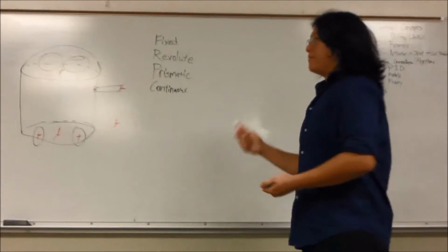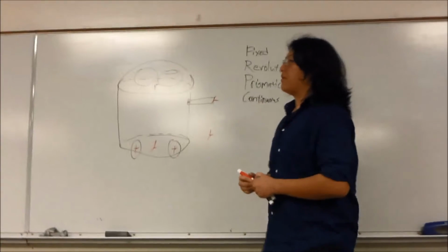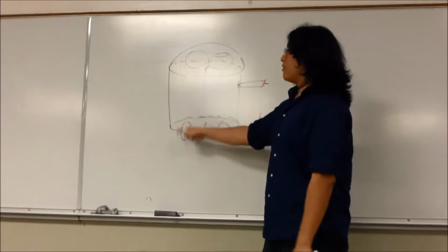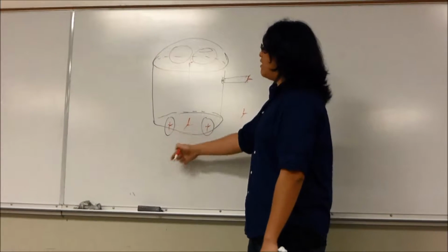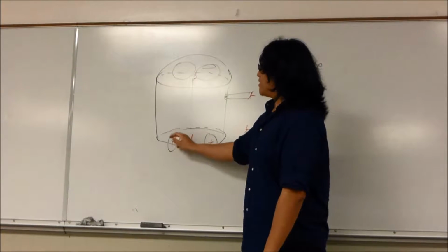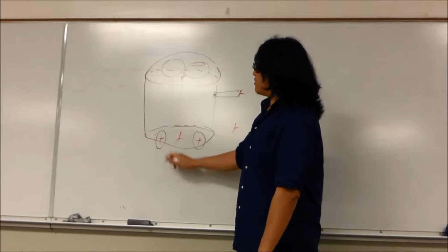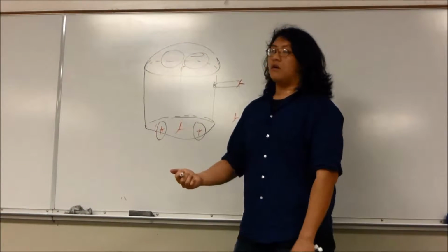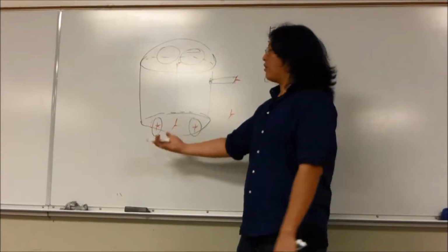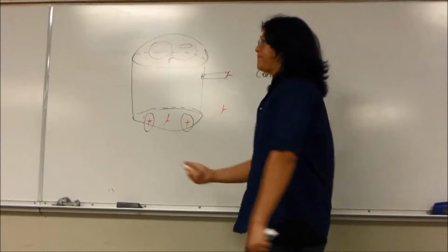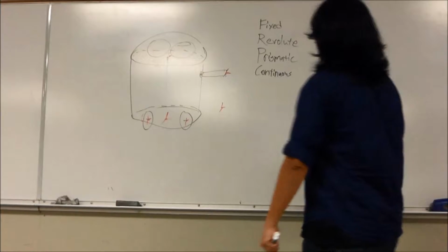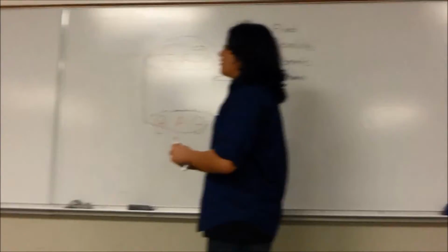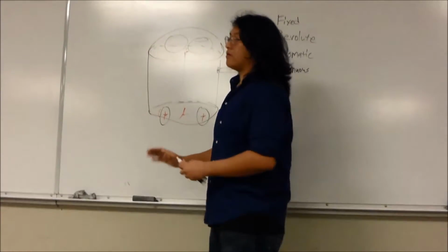However, there is actually some scheme as to where, if our actuator turns a certain amount, we know the diameter of this wheel on the floor, and if we turn it a certain amount, we know how much this joint here is going to rotate. Or we can perceive that by our encoder or feedback, if we have encoders on the wheels or something like that. And referring to how the wheel is actually moving would be in joint space.